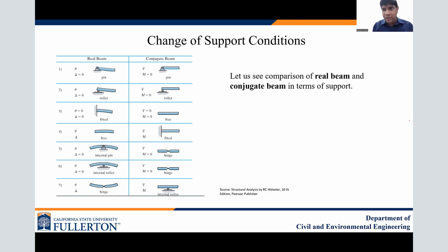We do not know the values, but at least we know that shear and moment is there. Similarly, slope and vertical deflection is there in the free end. So fixed becomes free, free becomes fixed. If we consider external pin and external roller, what is the condition?